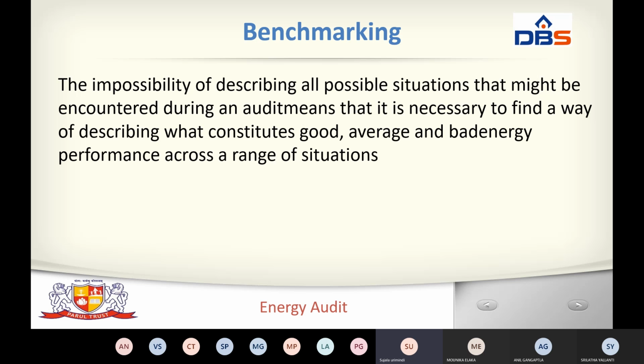So what is a benchmark audit? What is the basic of the benchmark audit? Benchmark audit means the first analysis consisting of a preliminary whole building energy use analysis, based on the analysis of history, utility use and cost, and the comparison of the performance of the building to those of similar buildings.